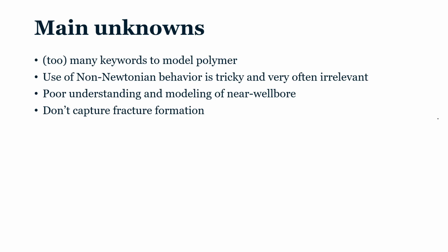If you don't capture fracture formation, that's exactly what I say. Some people try, some others do, but not everyone, not for every project. So it's something you need to assess in the field first. Do you have them and will you have them? And if the answer is yes, you need to put them in your simulation. Maybe not using negative skin, it's a bit cheating, but find a way to really make something dynamic, moving and changing over time.